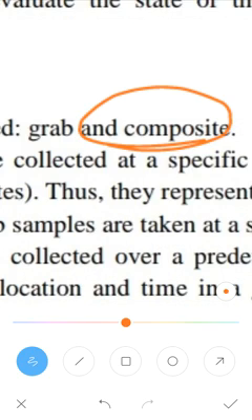Some preservatives can also be added to the sample bottle at the initial stage so that the samples can be preserved as they are collected. A composite sampler running over a period of weeks or a month should undergo routine cleaning of the container and sample lines to minimize sample growth and deposits. So that's about the composite sample.